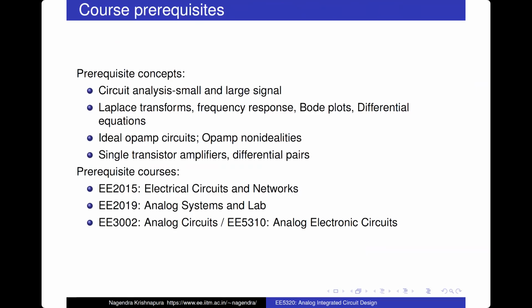So the idea is that because poor accuracy is sufficient, you can calculate this weighted summation in analog and get the final output instead of digitizing each one. And maybe that final output you digitize. This way you will save power. And this is mainly intended for what are known as edge devices, things that work on batteries and so on. Okay. So that is there. Again, for that, the specifics of the circuit we won't deal with, but whatever circuit design techniques we use, you can use them there also.